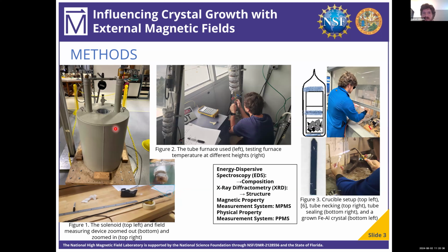After mapping the magnet field, we had to test the furnace and determine that its set point temperature was actually corresponding to a thermocouple temperature inside. So here in figure 2, you see Benny Schundelmeyer, who I worked with, and we moved a thermocouple through the furnace as its set point temperature was changing to ensure that the temperatures weren't too divergent from one another.